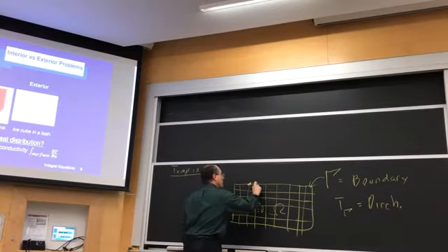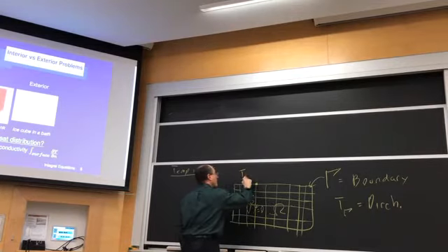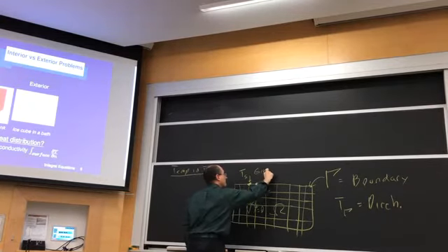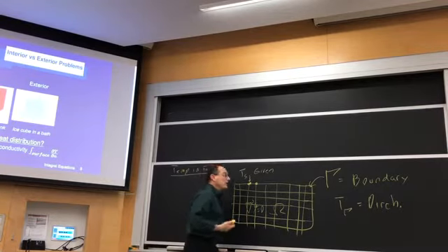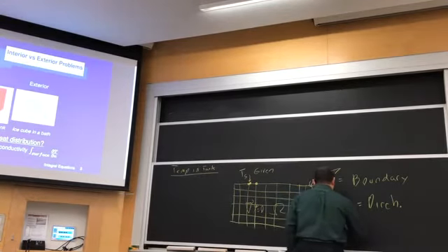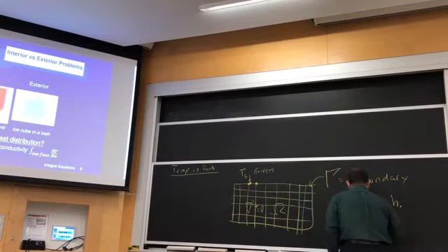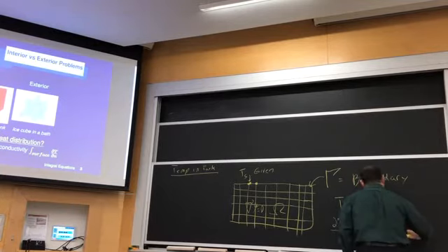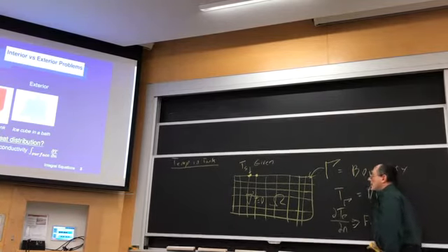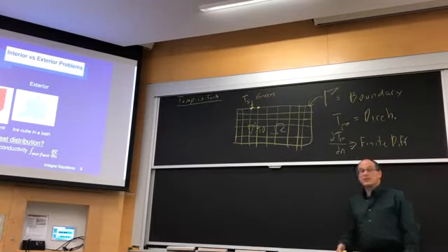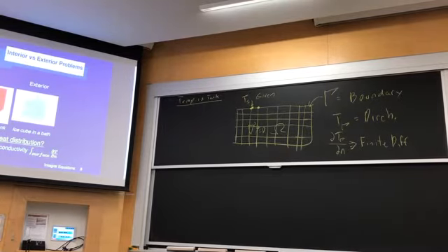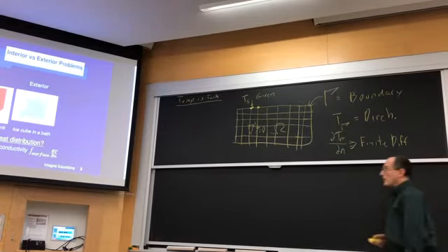So you know what the temperature is at these surface points. That's given. How will you find the normal derivative of the temperature? Using the interior points. Yeah, you use the interior points and you take differences, right? You can get dT on gamma dn using finite differences. Or if you're doing finite element methods, you can use the basis functions and differentiate those to get the normal derivative. But that's the way you think about solving for this kind of thermal conductivity problem.